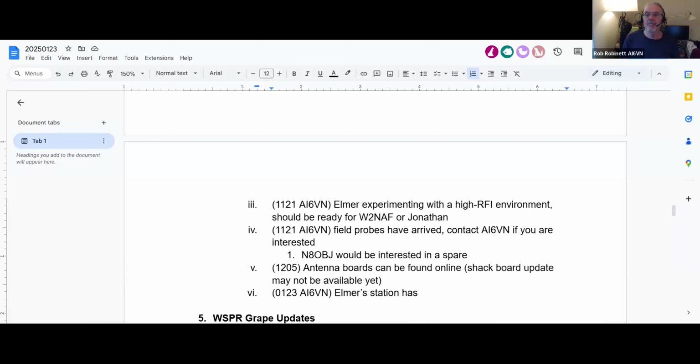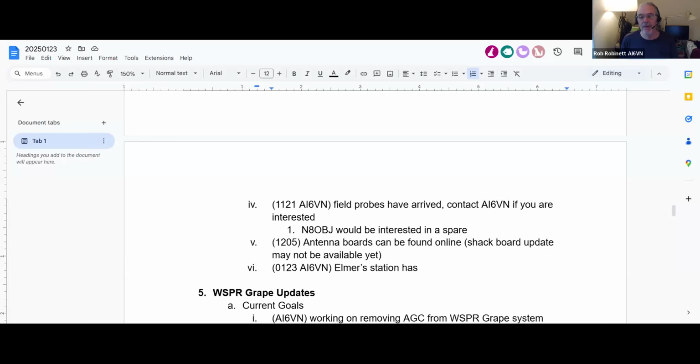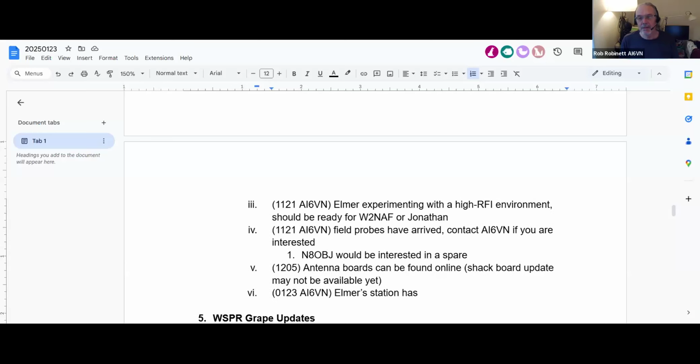FM stations are a tremendous source of problems for active antennas of any sort, whether it's Glenn's single antenna or the DX Engineering one. Identifying when your reception is impaired by local broadcast stations, whether AM or FM, is an important element in the evaluation and monitoring of any one of our sites.